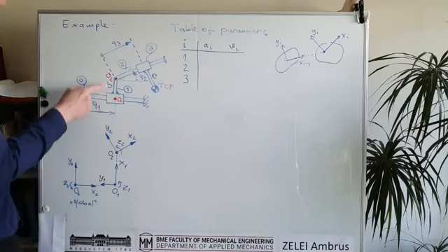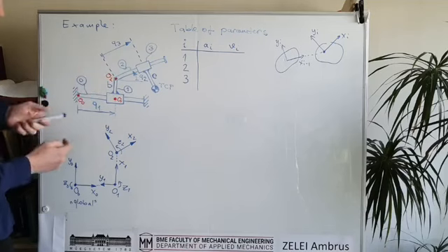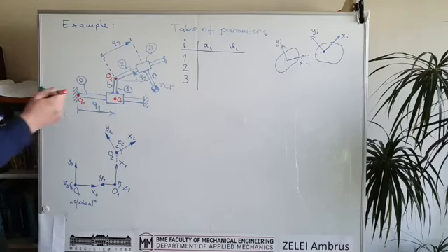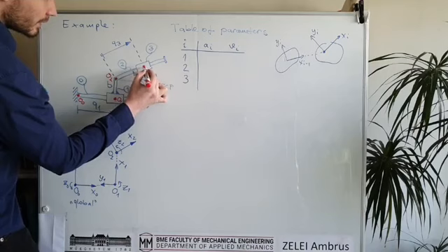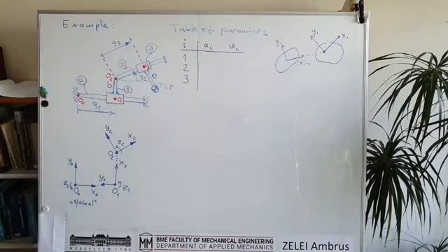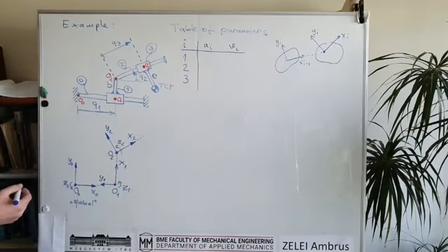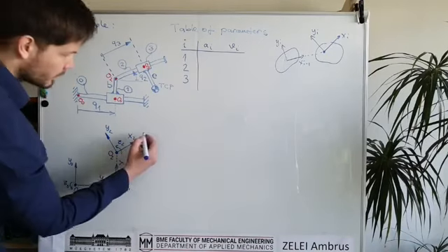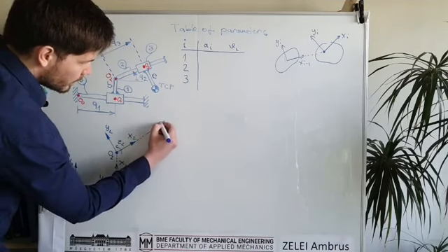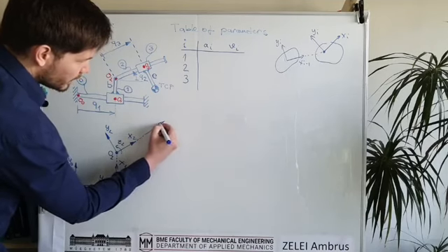So now this is the origin, which is here in this figure, and we want to move our third coordinate system here. So this is O3 here, and if you want to move there, then we need again a translational joint, and no need for any other transformation.